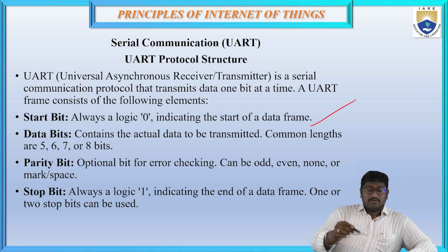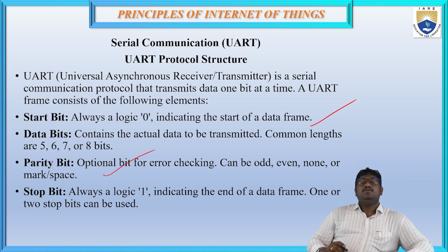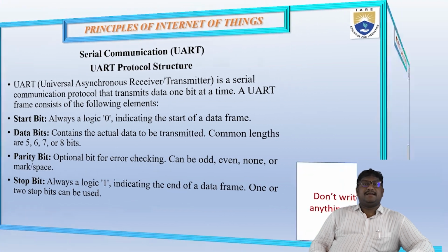Coming to parity bit, which is an optional bit for error checking, which can be odd, even or none. Coming to stop bit, which always uses a logic 1 indicated at the end of a data frame. 1 or 2 bits can be utilized.